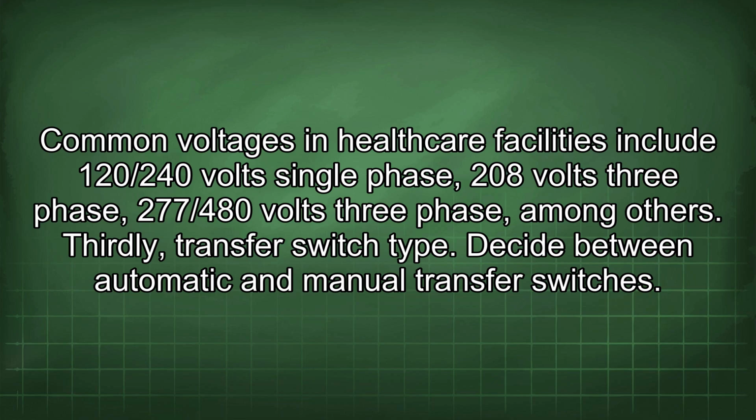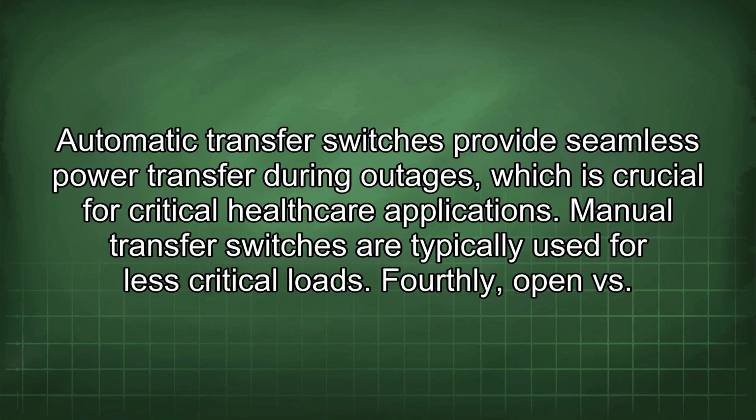Thirdly, transfer switch type. Decide between automatic and manual transfer switches. Automatic transfer switches provide seamless power transfer during outages, which is crucial for critical healthcare applications. Manual transfer switches are typically used for less critical loads.